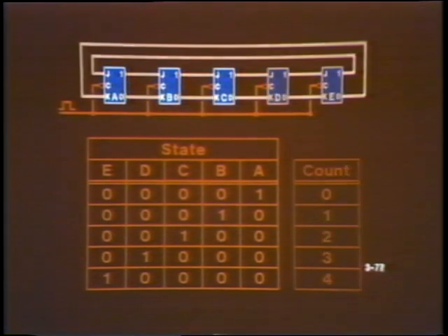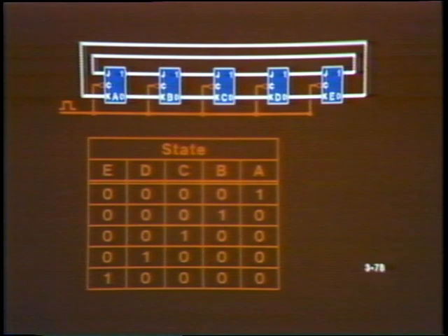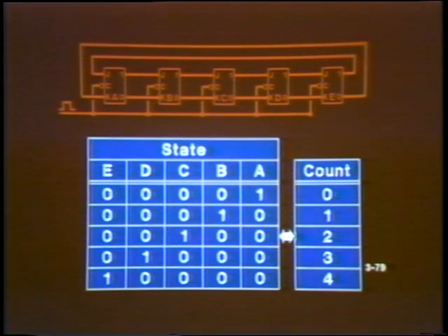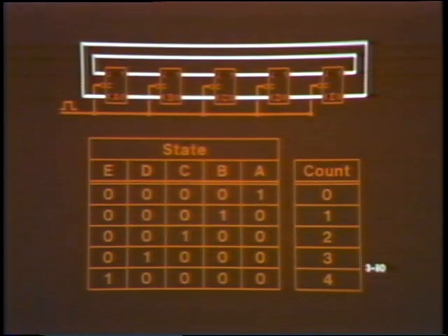However, the ring counter does have its advantages. It's an extremely simple circuit with few interconnections and no gates whatsoever. In some situations, the cost of 2 extra flip-flops may be less than the cost of more elaborate interconnections. The ring counter vividly demonstrates the ideas we discussed a moment ago. The design of non-binary counters depends on a choice of which states should represent which counts, as well as the feedback loops which implement the chosen counting sequence.